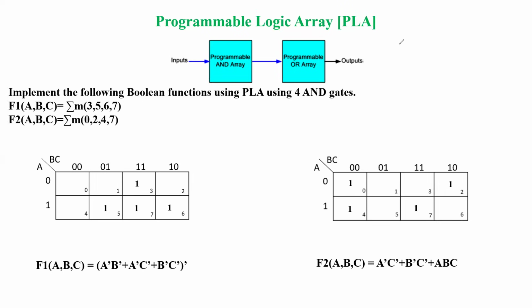Hello. Now we are going to discuss the programmable logic array. The basic concept behind PLA is that both the AND array and the OR array are programmable. Here we are trying to design two functions. These functions have three variables A, B, C, and the corresponding min terms are given. The condition is that we have to design with the help of four AND gates only.